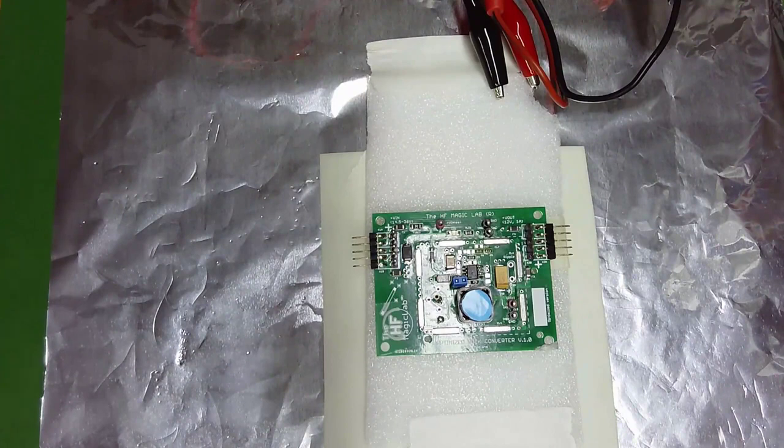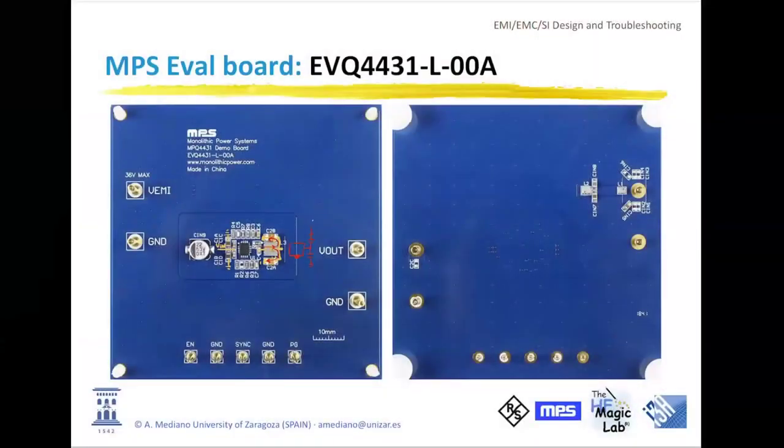Okay. Is there a big difference between semi-shielded and full shielded inductors to reduce noise at the output? Or is it better to have a smaller size in the inductor? I prefer the small size inductor, but obviously a fully shielded inductor is better for EMI. Okay, but where you put the inductor and how is the orientation and how is the size is really important. And additionally, in a previous comment, let me show you this screen. You will see that in many inductors, the manufacturers put a dot.